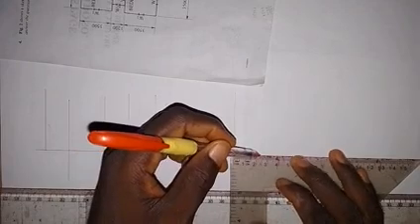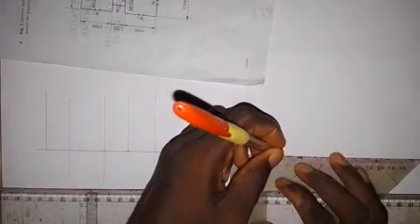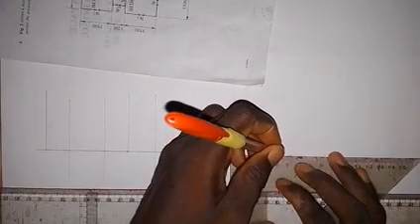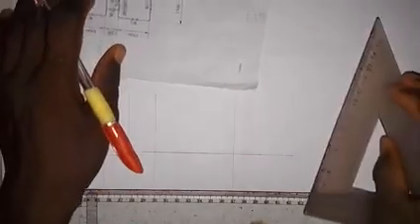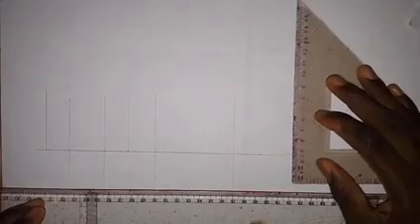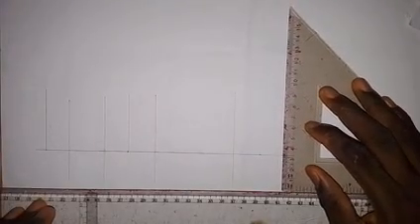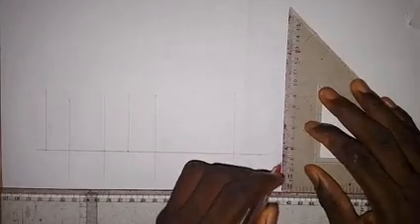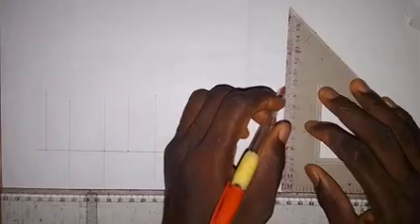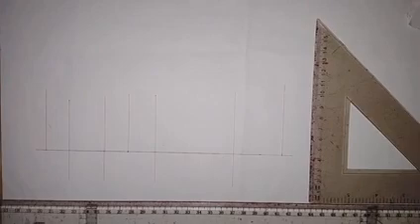So I have to take a measurement of 44 millimeters from here. I need to extend this line. So this is 44 millimeters at this point. At this point, we have to draw a vertical line, so we take it up. The cutting plane does not touch it, so we only see the edge of that wall. So these are the 4 walls that we are going to produce their foundation.